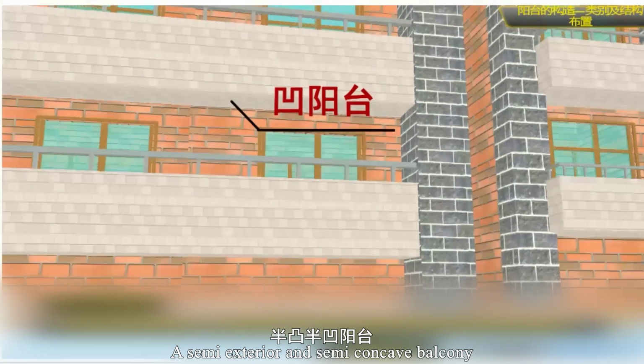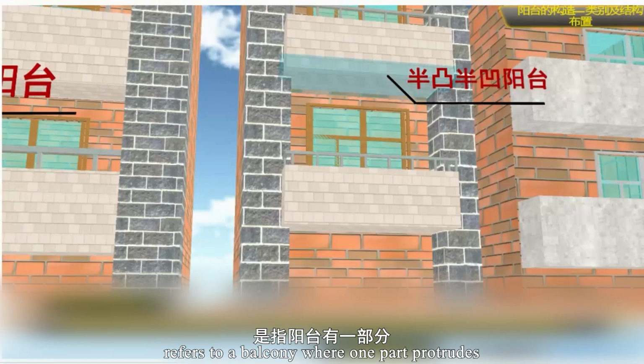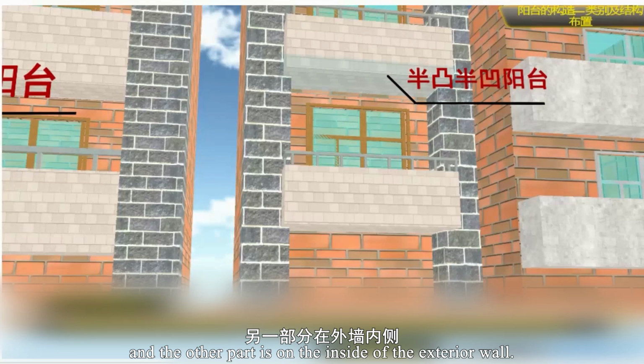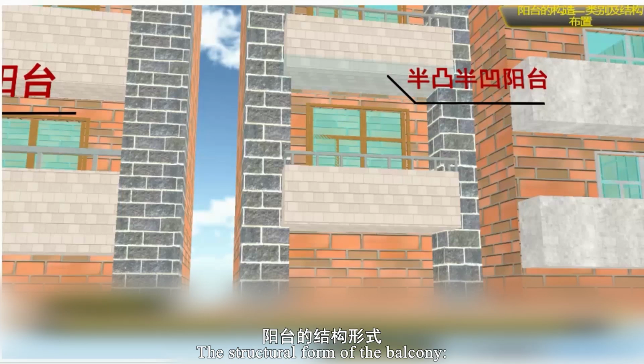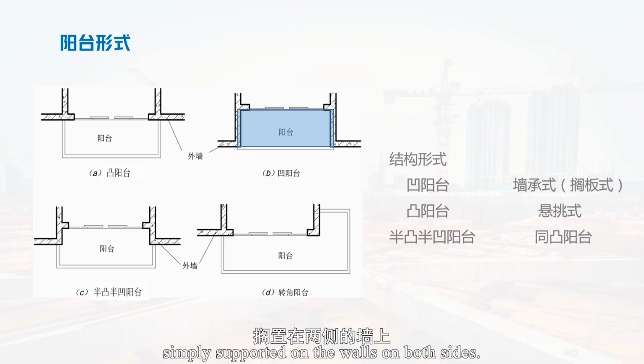A semi-convex and semi-concave balcony refers to a balcony where one part protrudes beyond the exterior wall of the building, and the other part is on the inside of the exterior wall. The structural form of the concave balcony uses a wall-support type, also known as shelf type. It refers to placing cast-in-place or prefabricated balcony slabs, simply supported on the walls on both sides.